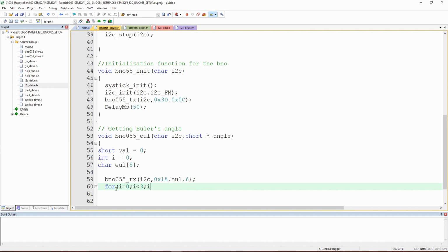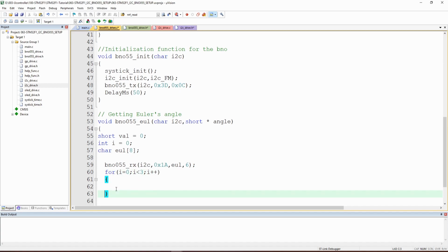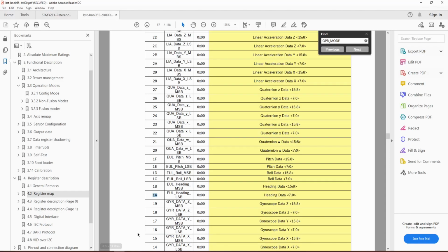So what we are going to read from our end is like this. For each register, we need 3 angles. Why are we reading 6 registers? So if we go back here, because each of the registers has the low LSB and MSB. So for both of them, it's a 16-bit value, and it's extremely important to know that it's a 16-bit value.